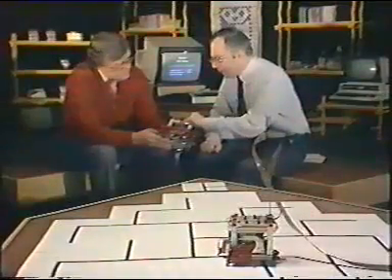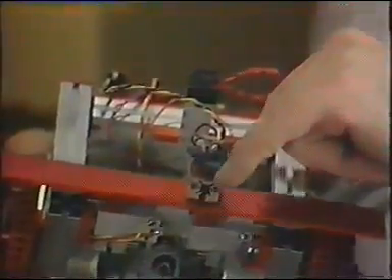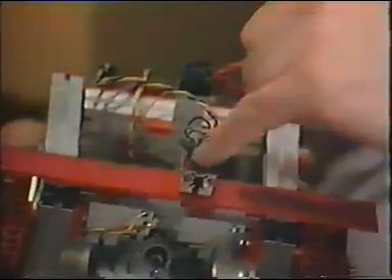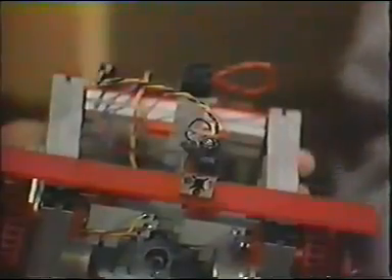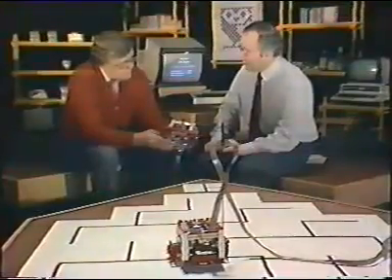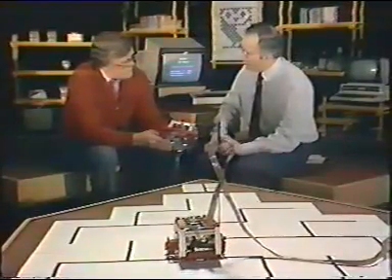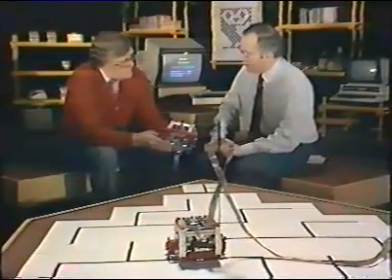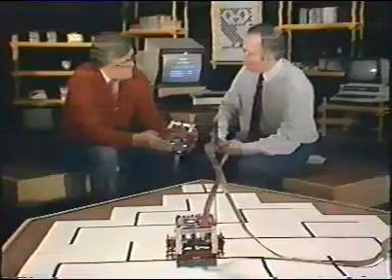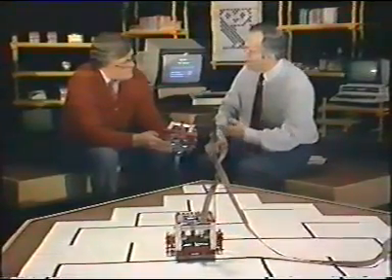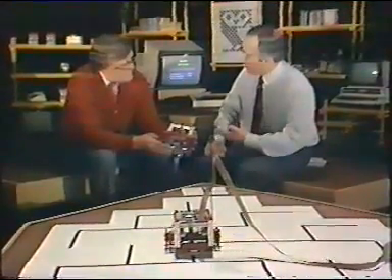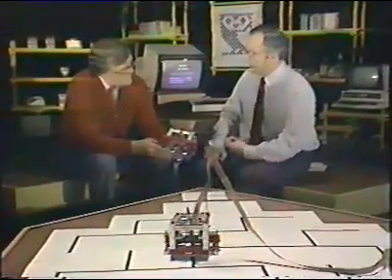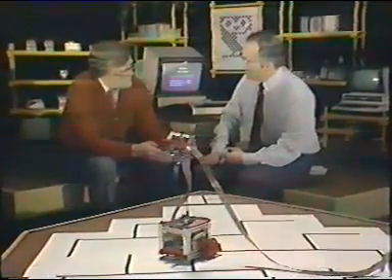This one's really rather different. This sensor emits infrared light on this side, which is reflected off a surface, and then the infrared is picked up here. So it can follow either a white line or a black line and determine which it's on. Now, it's actually an analog device, but the computer senses whether it is above a 50% level, whether it's above grey. If it's brighter than grey, it says that must be white. If it's darker, it must be black.